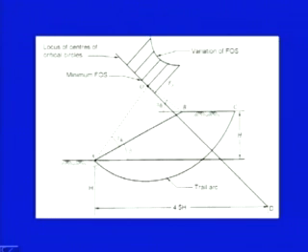So, here this is the slope AB, and this is the slope angle beta. With respect to AB, we have drawn angle alpha A and drawn this line. Similarly, get alpha B from that table corresponding to beta and draw a line here.